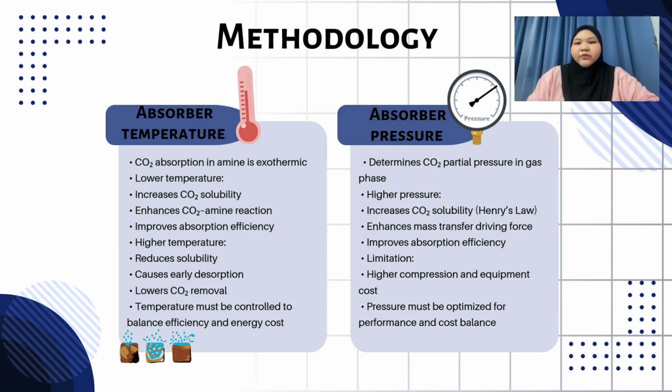Absorber pressure is another key parameter that affects CO2 absorption performance. It directly influences the partial pressure of CO2 in the gas stream. According to Henry's law, higher CO2 partial pressure increases the solubility in the liquid amine, which improves the driving force for the mass transfer. When the absorber operates at higher pressure, CO2 absorption becomes more effective because more CO2 can be transferred from the gas phase into the liquid solvent. This results in higher solvent loading and better CO2 removal efficiency.